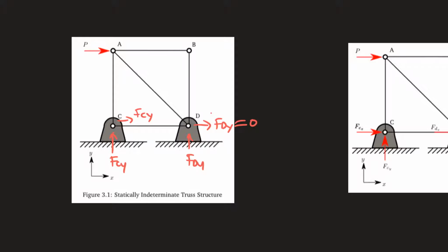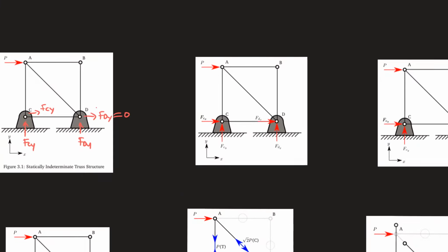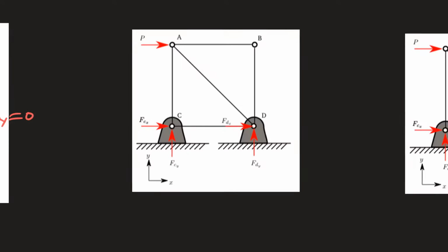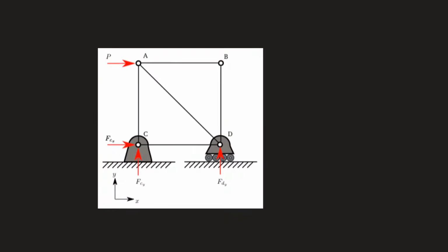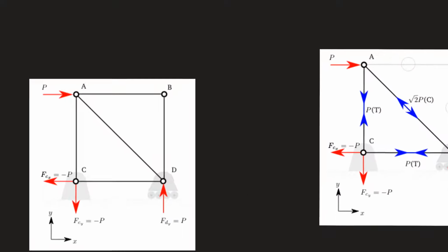That's my redundant reaction. So what that has in effect done, in fact, sorry, this next one I just marked here, but what that's effectively done, it's replaced that with a roller support. And you don't need to draw it like this, but it just helps you to visualize what's going on. So it makes sense that if we're loading in this direction, we would expect this structure to shift towards the right-hand side to increase it in the direction of x.